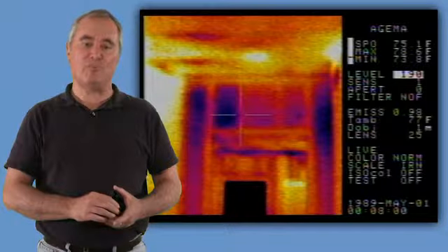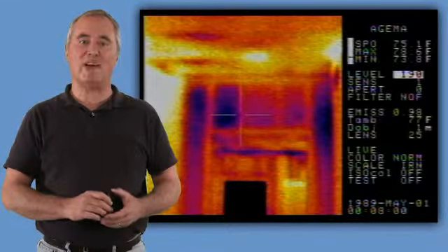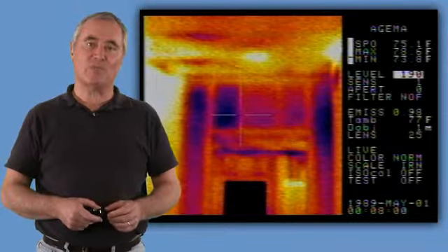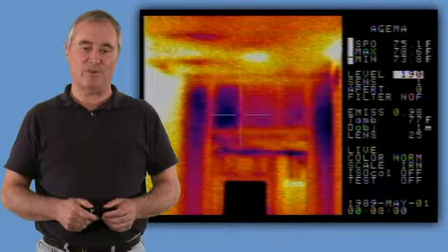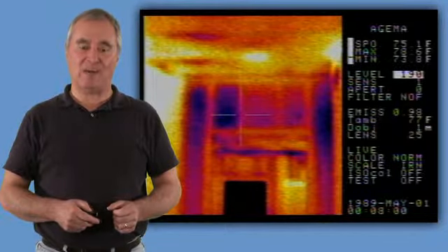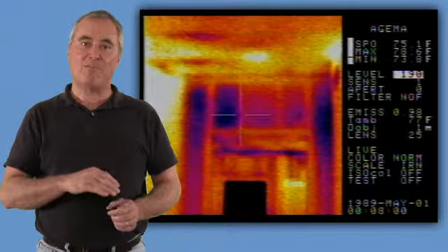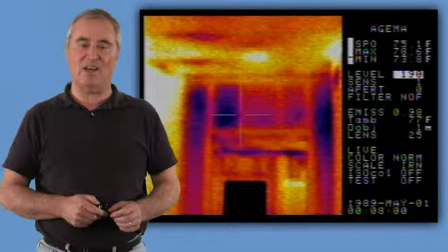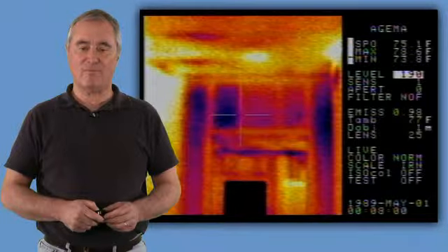Here's a newer building. Again, in the winter time, we see the cold air leaking down into this big interior interstitial space, turning it into exterior wall, even though as we glance at it, we think it's completely interior. But because we're missing the fire stop at the top of that wall, it's all open to the attic, greatly increasing air infiltration in that part of the house.